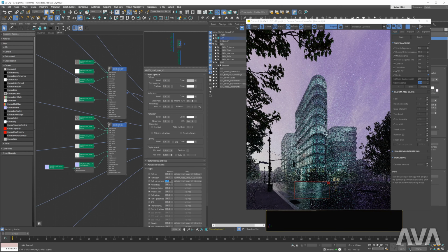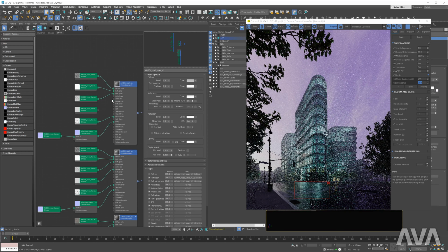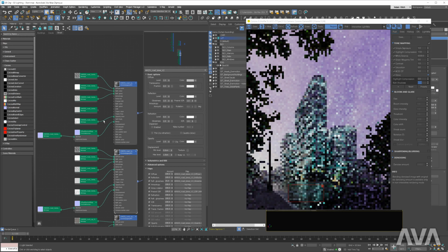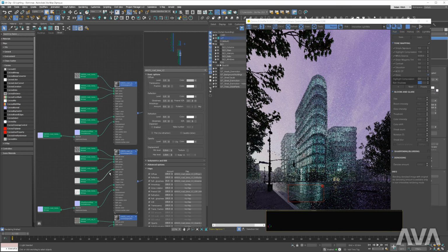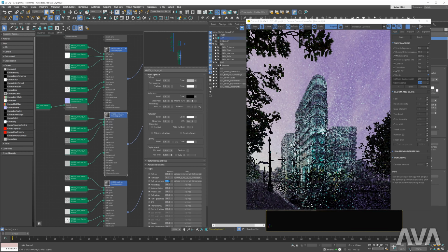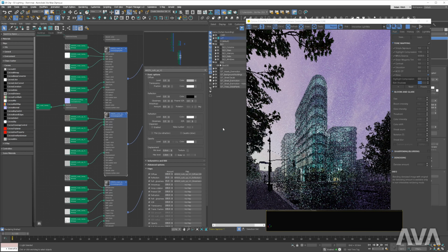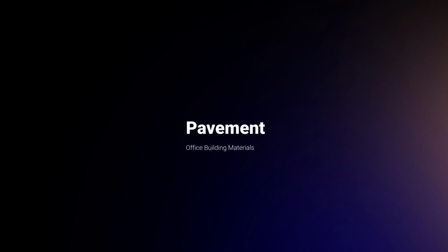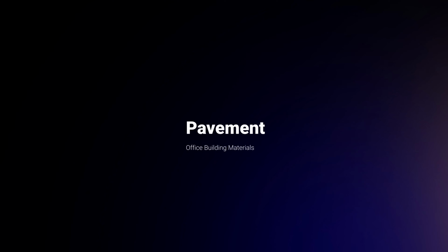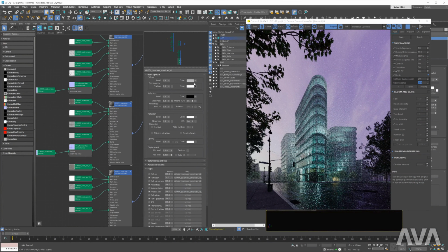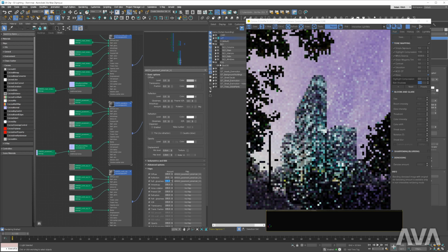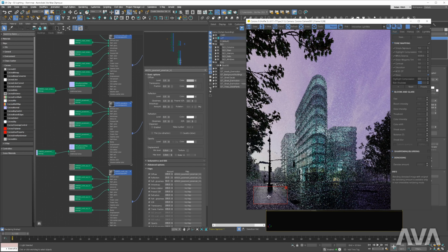This time we can change the reflection glossiness amount to 30. I will do the same here. Delete the map and adjust the value. Similarly as previously, delete the Fresnel IOR map. I want it to be quite reflective, so let's change the reflection glossiness amount to 50. Nice, I like it. The reflections make it look way better.